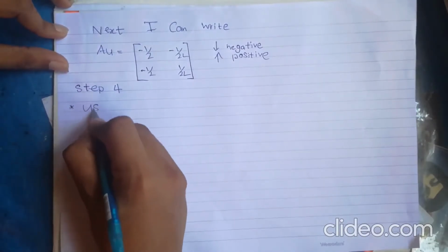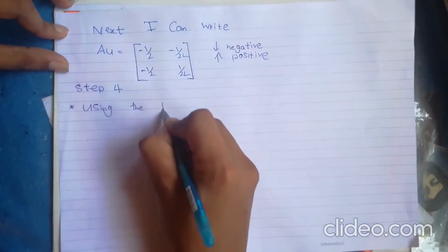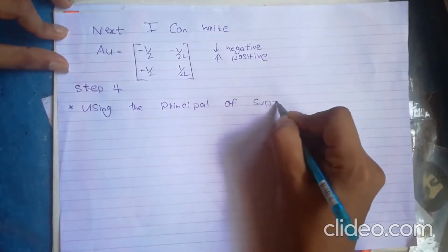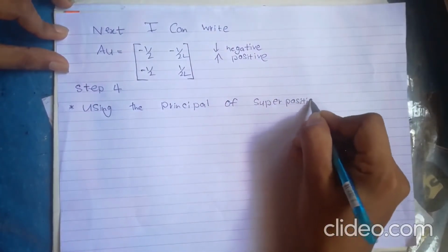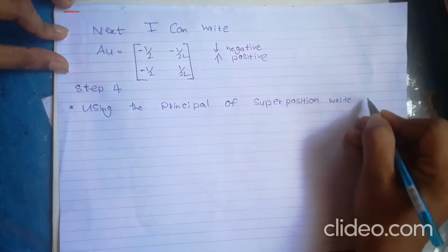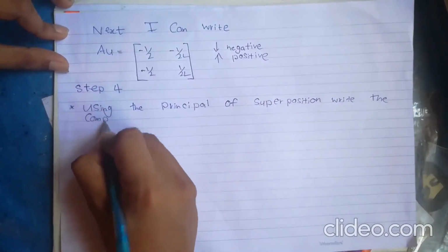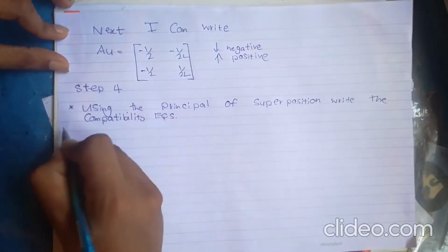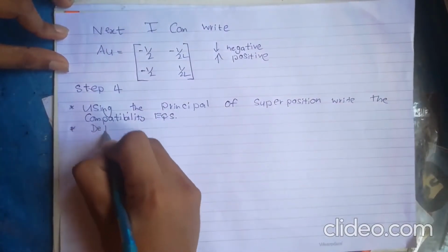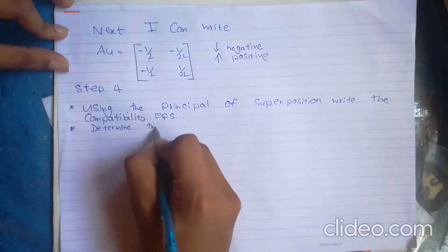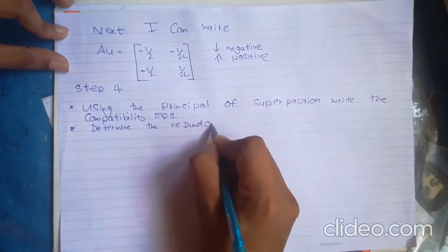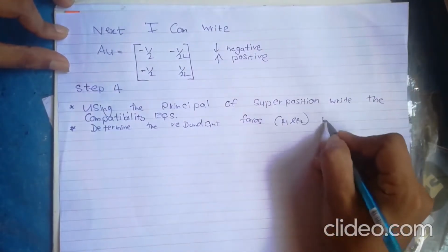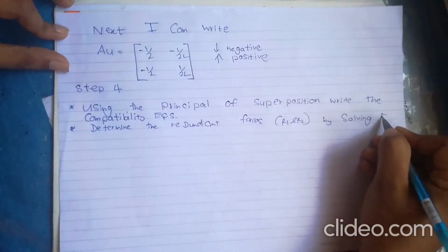Step 4. Use the principle of superposition, and write the compatibility equations. Determine the redundant forces R1 and R2 by solving these compatibility equations.